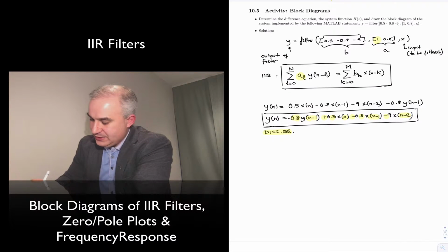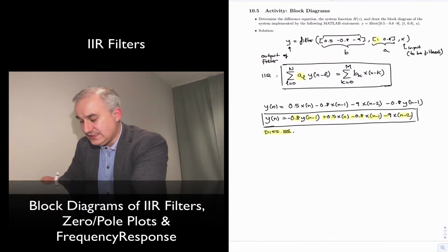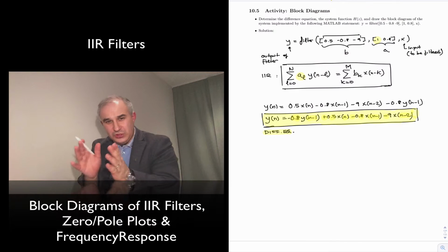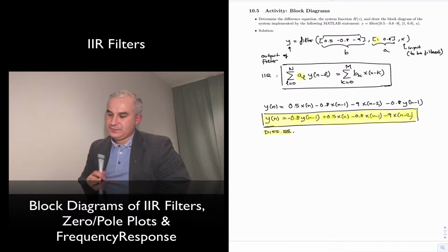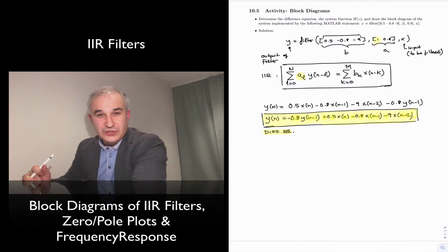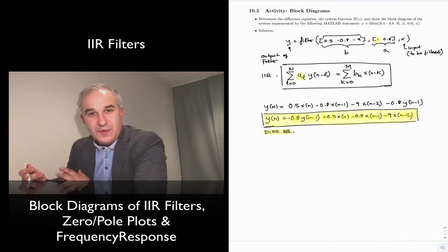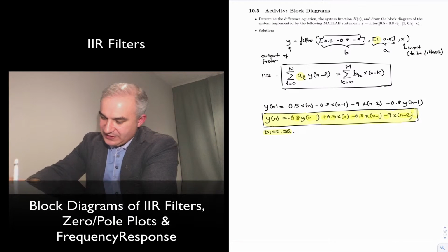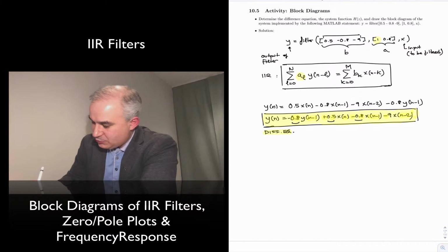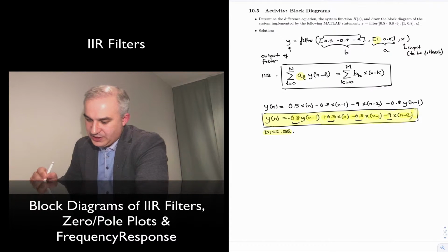and multipliers. You can implement this in hardware or directly, since these are operations that are in absolutely all processors, from the simplest microcontroller to the processor in any computer, to, of course, a DSP that has been optimized for these multiply-accumulate operations. So you can do several billions of these per second. That is how you implement these filters. Now, the problem of filter design is how to design these filter coefficients to achieve the frequency response that you want. So that was the first part.